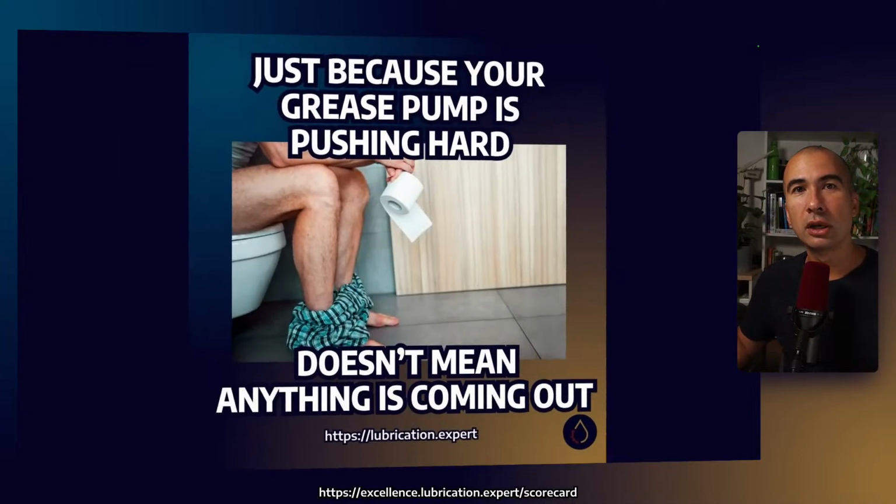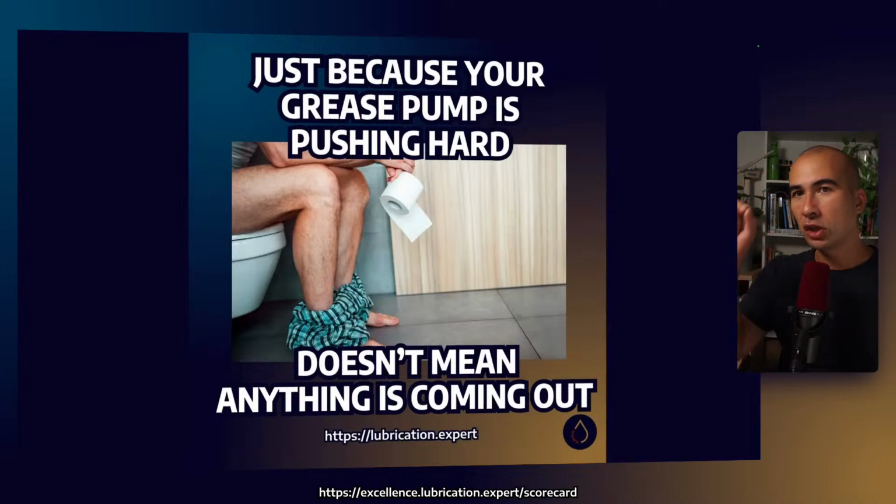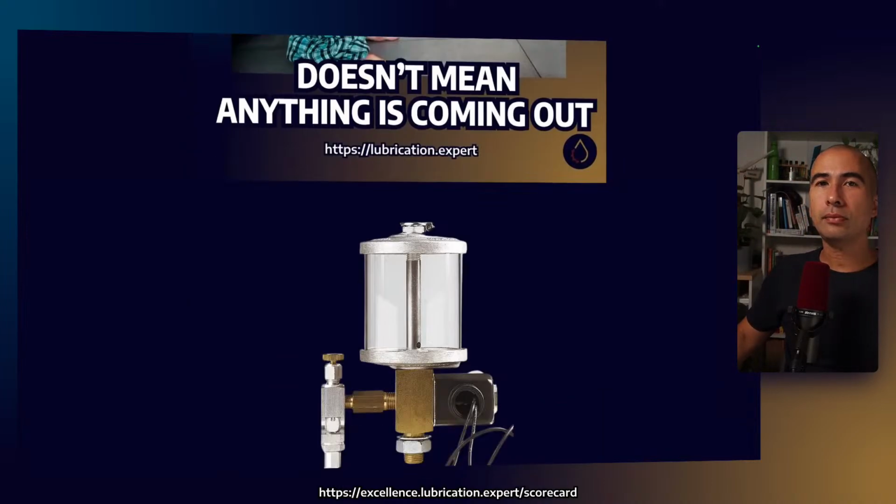Now, one thing to note, just because your grease pump is going does not mean that grease is being applied to the bearing, right? So I often see people will say, oh, but my grease pump was still showing pressure. Okay, but a lot of these grease distributors or grease valves will have an indication pin which shows whether they are actually firing or not, and it's part of standard practice in maintenance to ensure that those firing pins are actually going. All right.